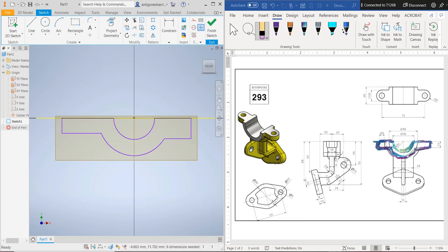Now, size of the geometry comes off of a different view. 72, that's the distance from centers. And then you have the radius of 9 on this side, which means you have a radius of 9 on the other side. What I'm looking at right now is this information with this information, because these are the two things I need to determine the edges of this part, okay?